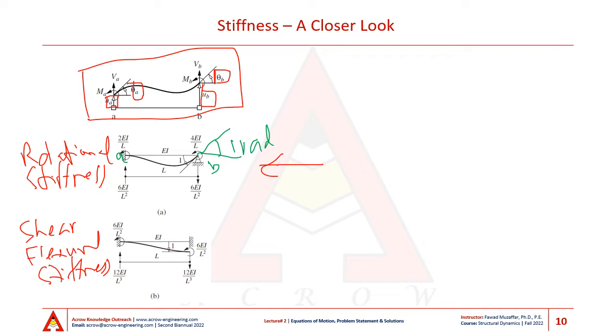This is a classical problem of indeterminate structural analysis which can be solved using any structural analysis method. I would prefer the moment area method to solve this, but this can be solved using slope deflection, conjugate beam, consistent deformation, or stiffness and flexibility approaches.